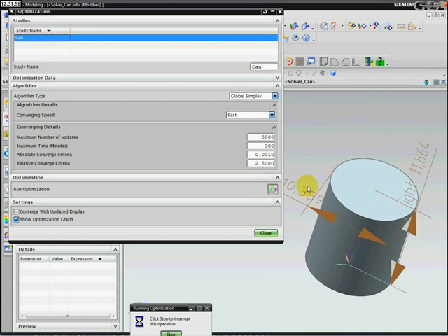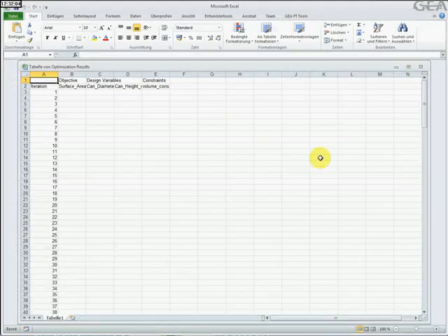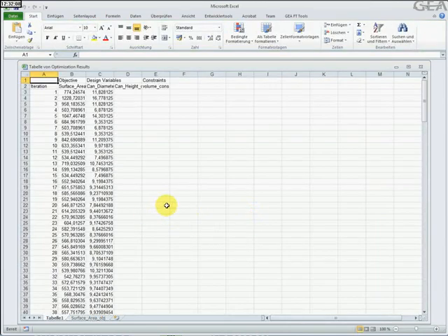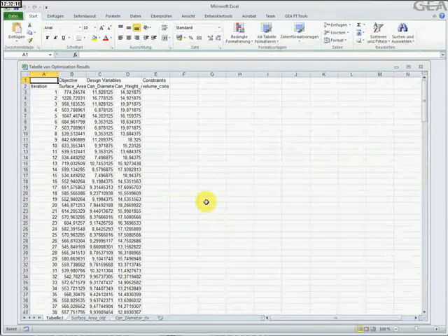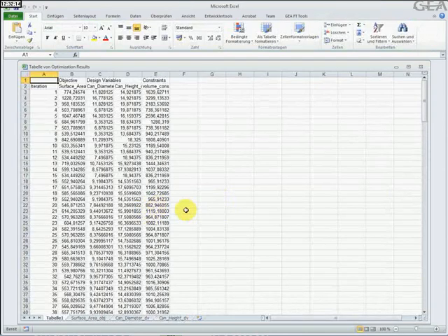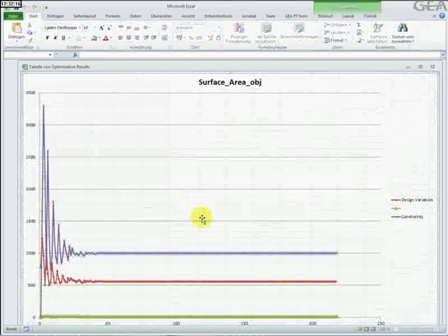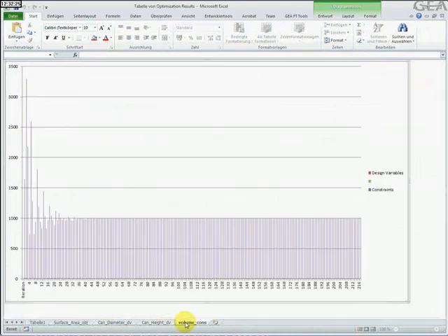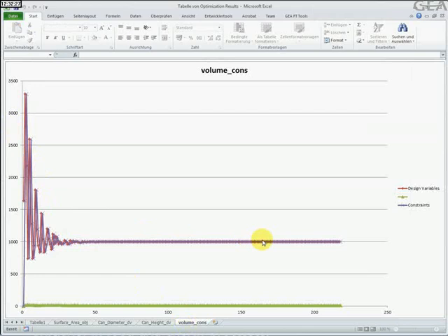In comparison to the Excel-based solver, this NX integrated one is very useful if you have a more complex design, with radii and so on, because those geometric formulas cannot be included in Excel, and on the geometric base of NX you can use those mechanisms.